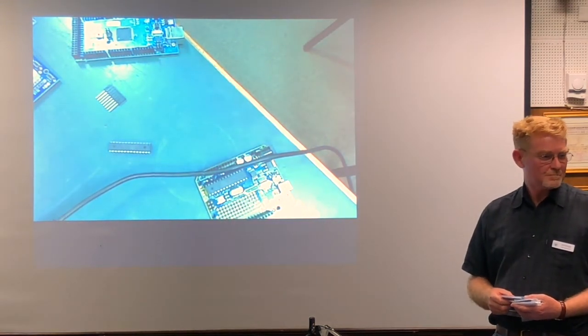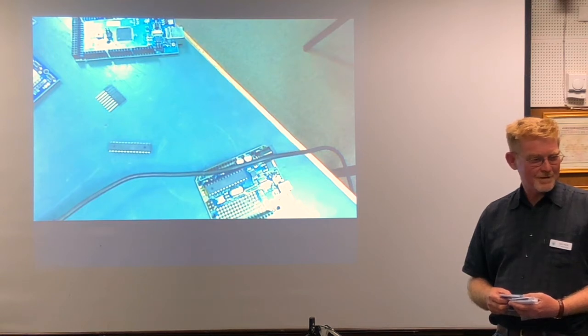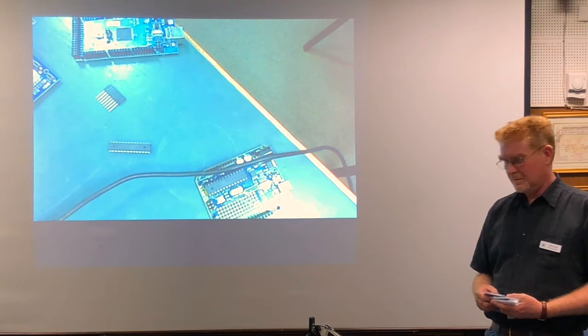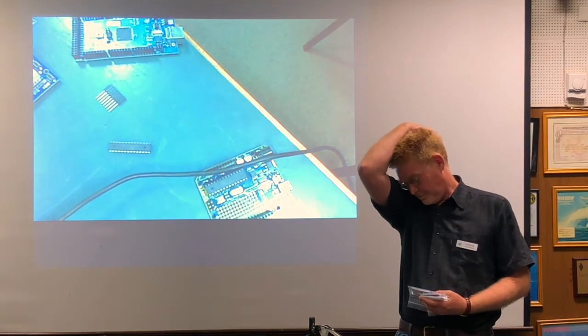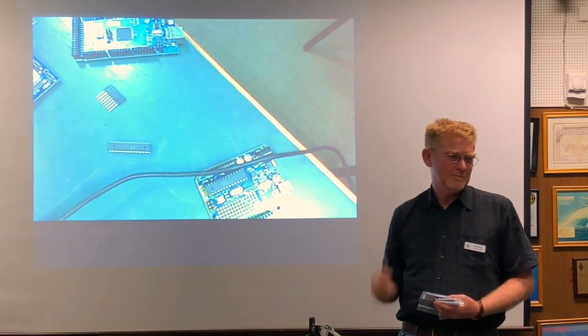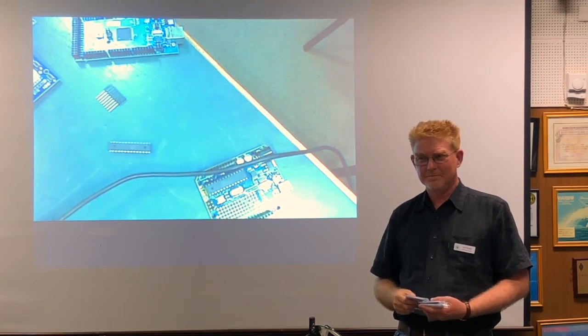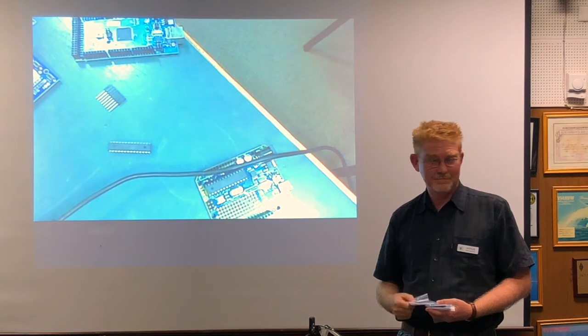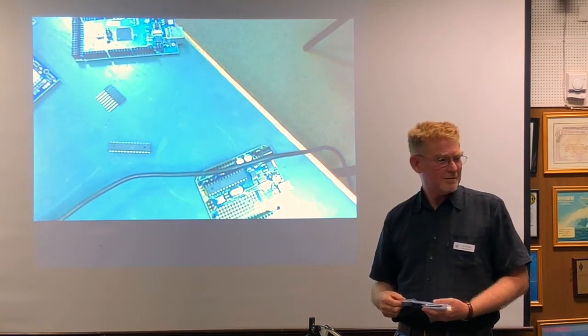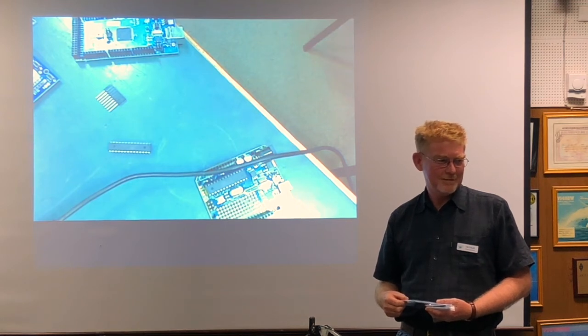Because there's the ones that don't have the USB on them. They've just got the USB header. So you buy a USB module, you stick it on the header, you program it, you take it off, and it's that size. It's postage stamp size. So if you need a little embedded controller, good and smaller. It's basically just the Atmel with a little bit of glue, and a couple of headers.